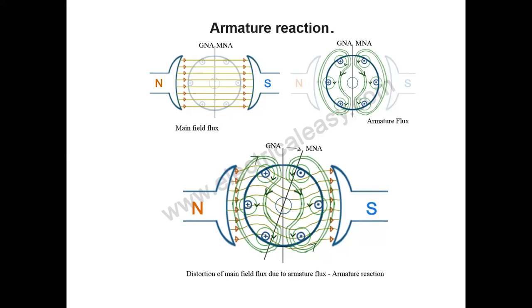It is the magnetic neutral axis when there is no EMF produced in the armature conductors, because they move parallel to the lines of the flux. The magnitude and direction of MMF producing the main flux is represented by the vector OFM. Actually, a vector diagram is there. That vector diagram we'll discuss in the later class.